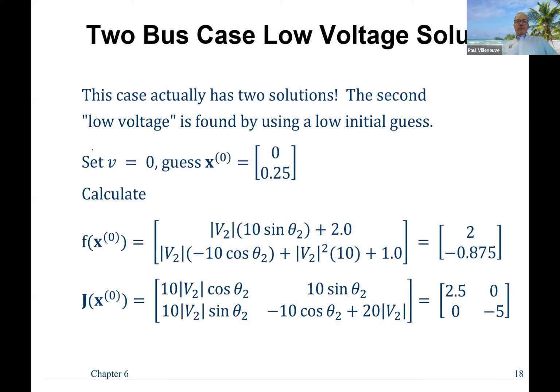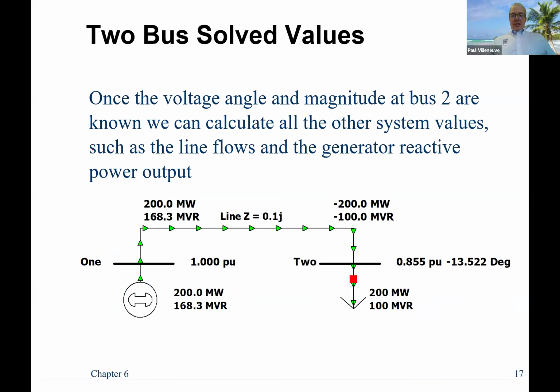And then your J, which you said is equal to 0. Which J, let's say we have 3 buses, which J are we looking for? Oh, no, it doesn't matter with 3 buses. What makes the G term 0 here? Z is equal to R plus JX. If I invert that, I have 1 over R plus 1 over JX, which is equal to G plus, or actually minus, JB. So because there's no real term, the G term is 0.